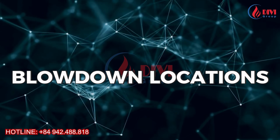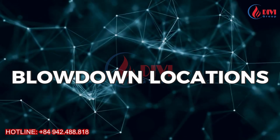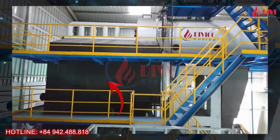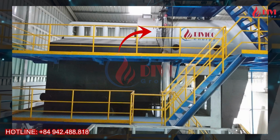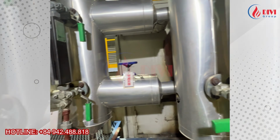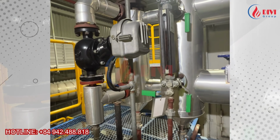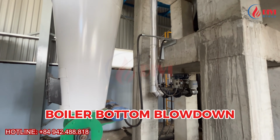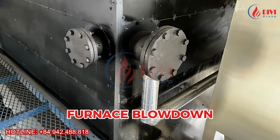Blowdown locations in the boiler. Typically, a boiler has several blowdown points, including boiler bottom blowdown, furnace blowdown, reflex gauge glass blowdown, transparent gauge glass blowdown, and surface blowdown. Among these, the boiler bottom and furnace are where the highest concentration of sludge and scale accumulates.